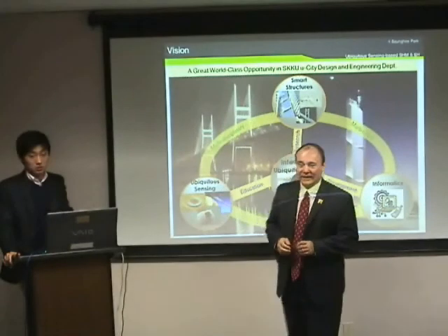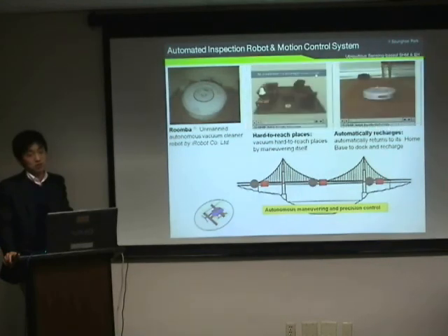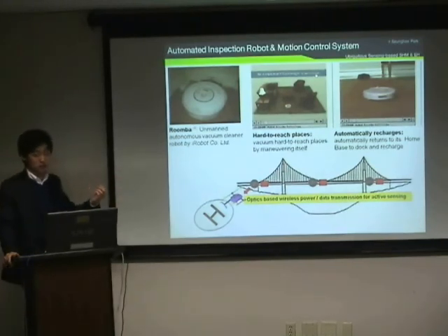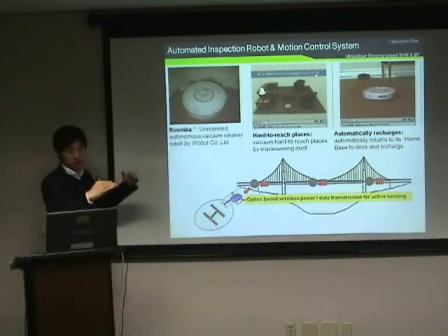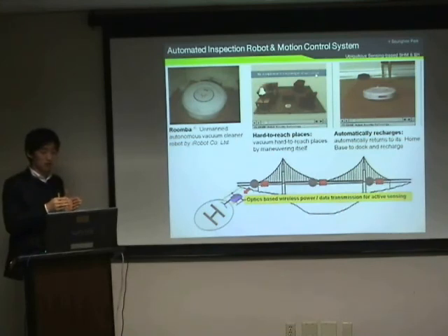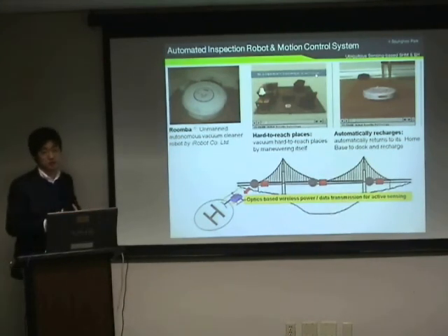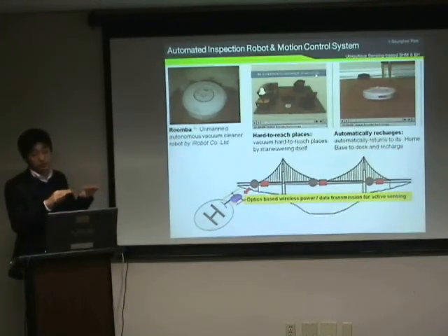Was your online damage detection based on a statistical pattern recognition, or had you trained your system before? We can use both approaches. Sometimes we need pattern recognition technique because we need to establish an optimal threshold to tell healthy condition and damaged condition, right? To do this, we can use statistical pattern recognition technique. But sometimes we don't need any threshold. In that case, we don't need to use pattern recognition technique. So we can do both approaches for structural health monitoring, whatever you want.